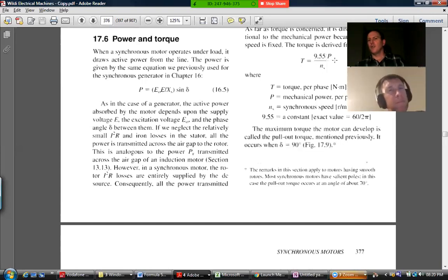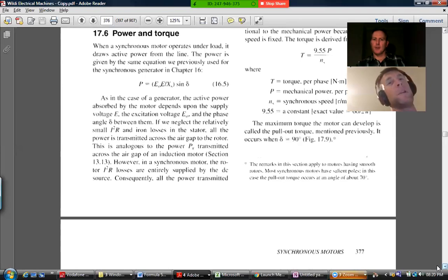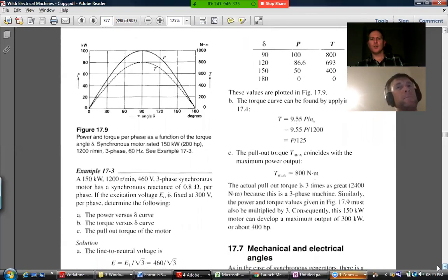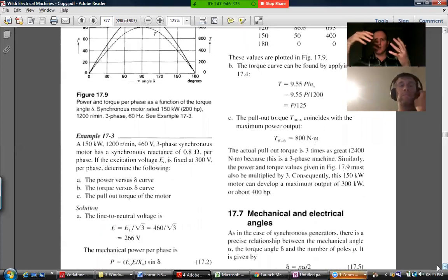So you don't need to remember funny formulas like that. You can just go power equals torque times omega. Again, the 2 are exactly proportional because the speed is fixed, assuming we've got a supply voltage with a fixed frequency. Okay, there's a bit of discussion here about a thing called reluctance torque versus just the normal attraction.